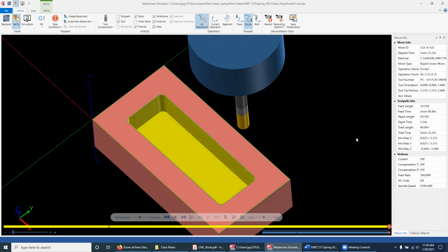So hopefully this is helpful to you if you're machining pockets where you want to get a little closer to the corners. And again, how close you get to those corners and exactly how close to those perfect 90-degree corners you get really depends upon the mechanical design and the functional aspects of the design you're pursuing. What you don't want to do is over machine and make a part more costly when it really doesn't need to be.